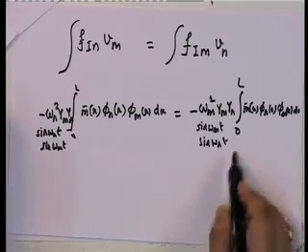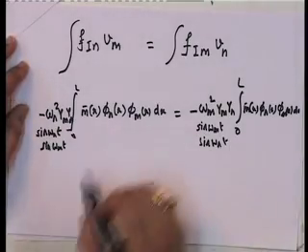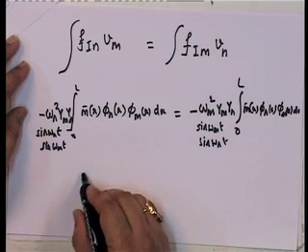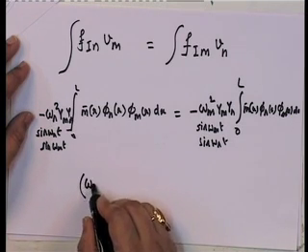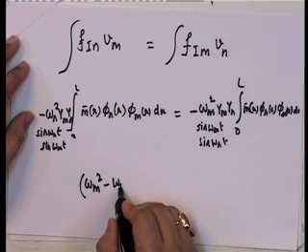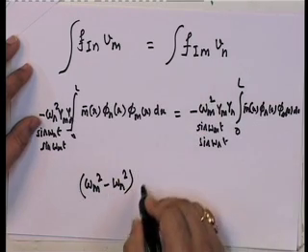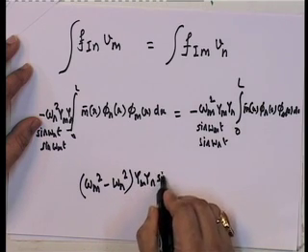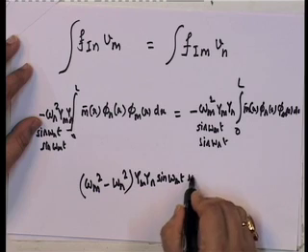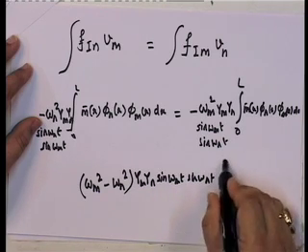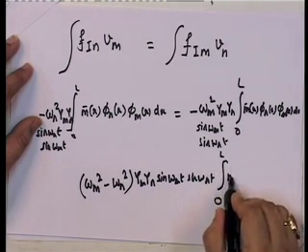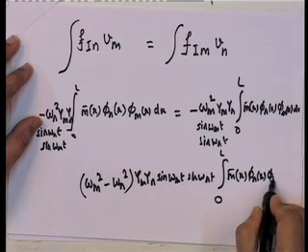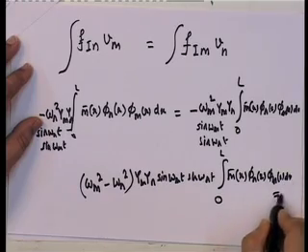Okay. So if I put these two, all these terms are the same. So if I put it in, I get the following. I get omega m squared minus omega n squared into all of this, ym yn sine omega mt sine omega nt, integral 0 to L m bar x phi nx phi mx dx equal to 0.